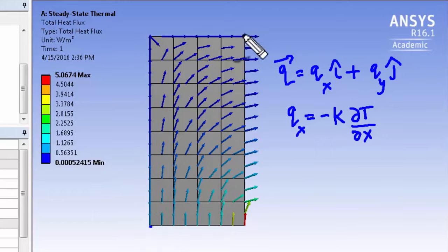And over here it's along there, and here you get something funky because at the corner you have two directions in which you cannot have heat flux, and this is a very small value, so we'll not worry too much about it. And then you can see that heat is flowing out to the fluid over here. And you can see that though the heat flux is supposed to be 0 at these boundaries, it's actually a very small value.